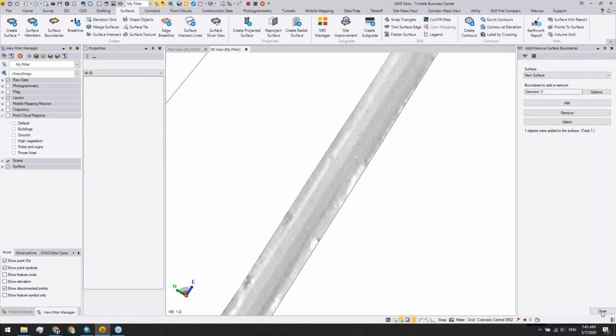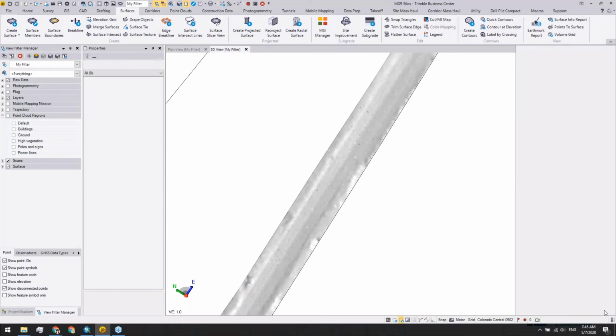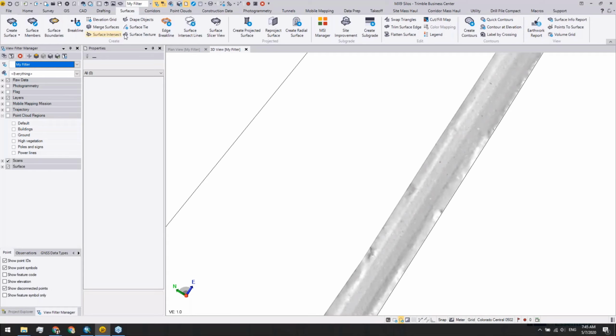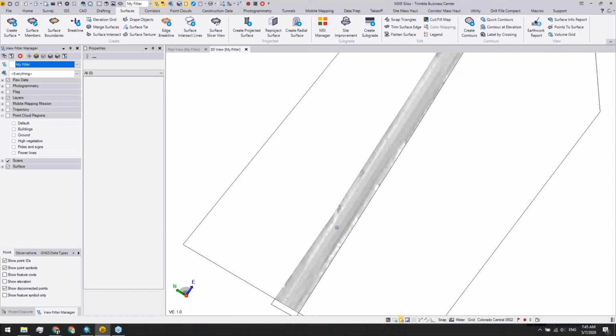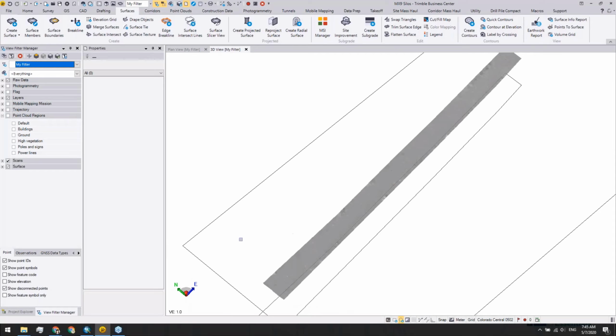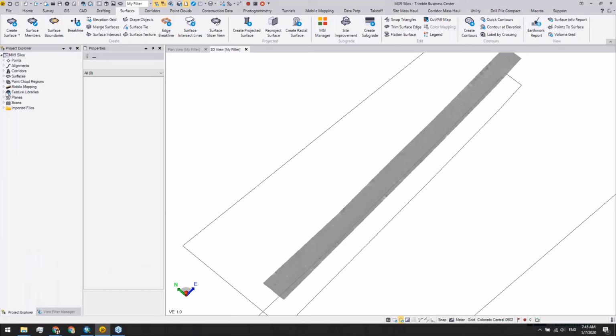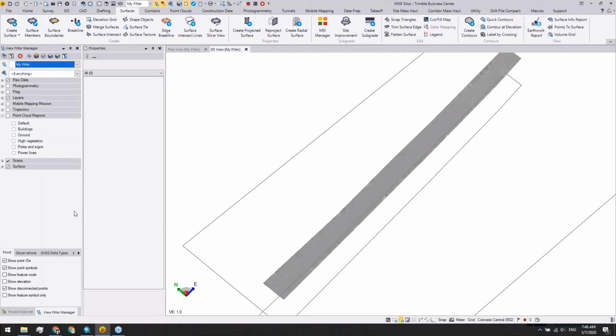All right, so once you have the surface created, you can do so many other things. For example, you can drape a texture, such as a Google Earth image or something, to the surface, or you can create contour lines on top of this surface. We probably won't cover all of them in today's session. Now the surface is created. I am going to create an alignment and then a corridor to represent this road. How do I do that?